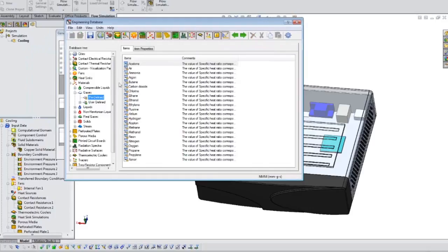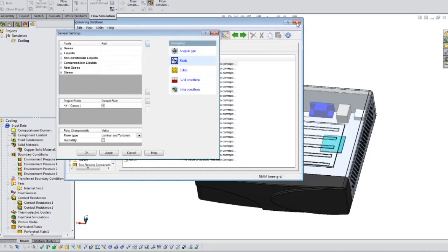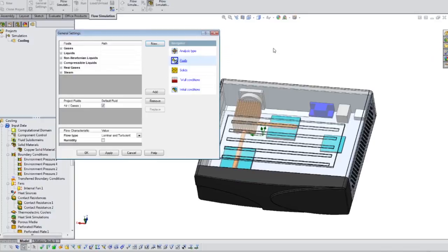And the last note that I have on there is discrete simulations, parametric sweeps, and optimizations. So most of the time when people are running and setting up analyses, they have specific things that they want to look at. Maybe they want to look at a flow simulation at 10 or 30 meters cubed per second. Those are really discrete simulations. Now, that sometimes is a specific way of using SolidWorks Flow Simulation, but often you have a lot of ideas that you want to look at, and that's where parametric sweep and optimization comes in. So with a parametric sweep, we can tell the software, you know what, I want to look at the whole range of flow simulations and flow velocities from 0 to 100 meters cubed per second at 10 meters cubed per second intervals.